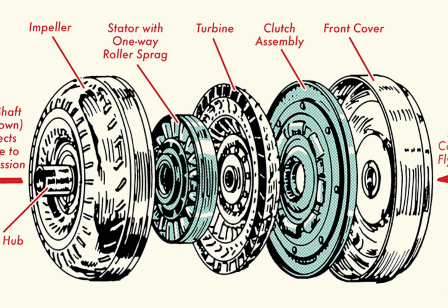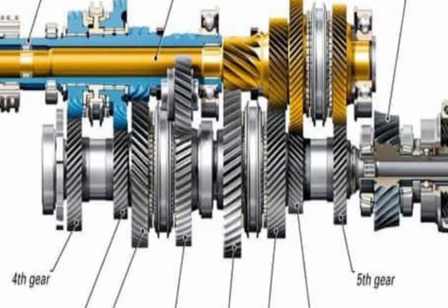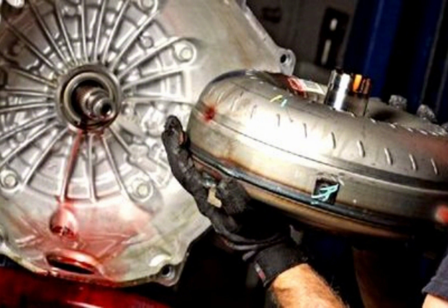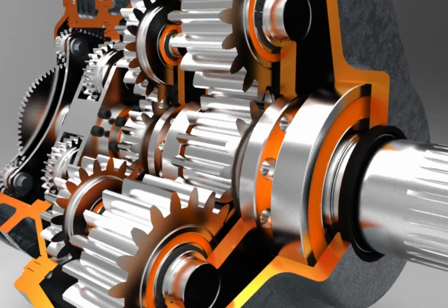Cruising. When driving at a steady speed, the transmission maintains a higher gear ratio for fuel efficiency. Slowing down, deceleration, downshifting. As you release the accelerator and press the brake, sensors detect the reduction in speed. The hydraulic system automatically engages lower gear ratios in the planetary gear set to provide the necessary torque for slowing down. Engine braking. The torque converter absorbs some of the braking energy, which helps reduce the load on the braking